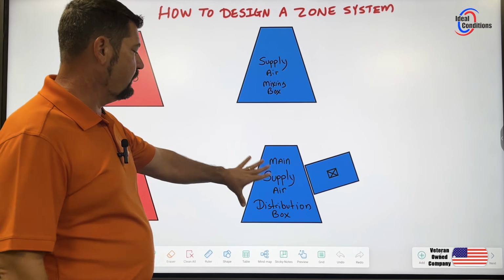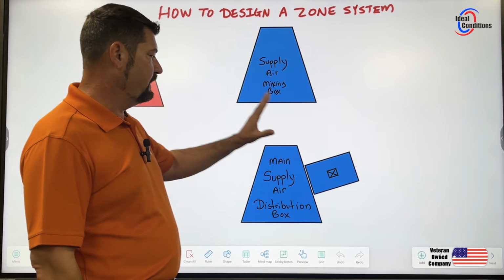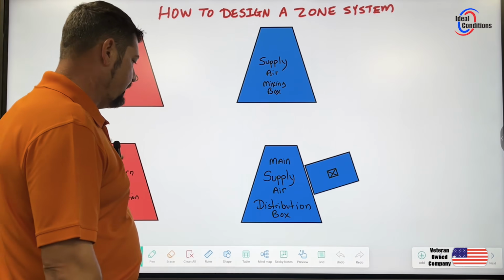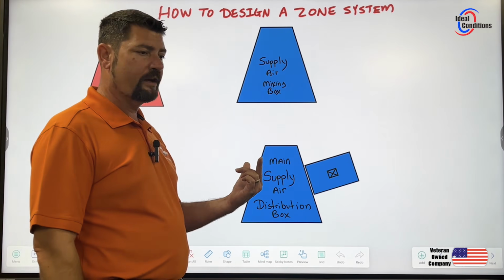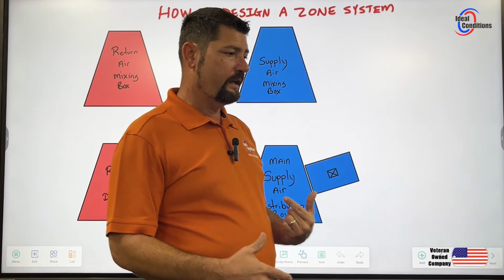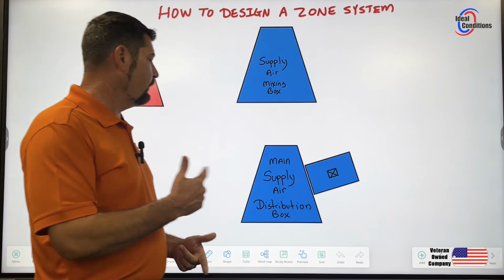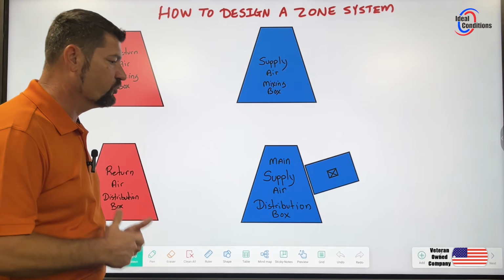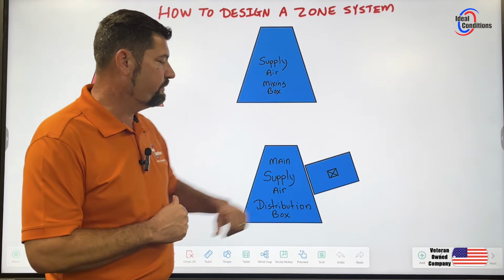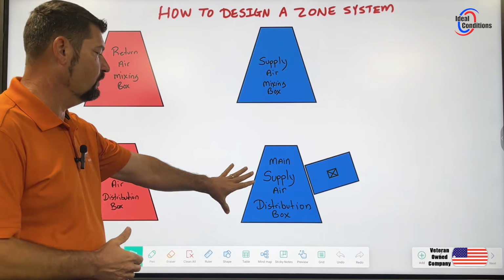By taking air out of the supply as dampers close down, that air is circled back around to the coil. Granted, it's cold air, and we'll get into that, but it allows the air handler to not struggle to breathe. So if we start closing these dampers down without bypass, we start having issues.